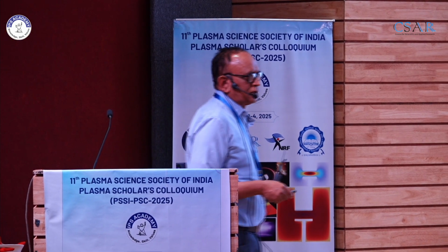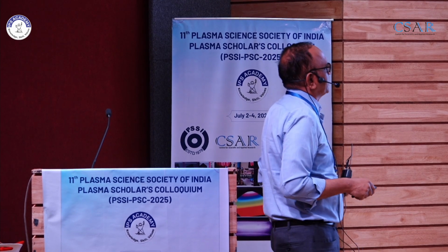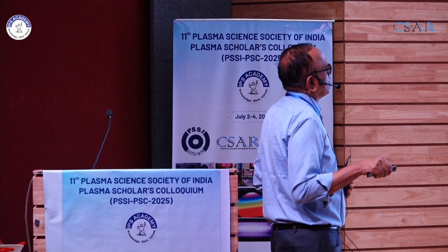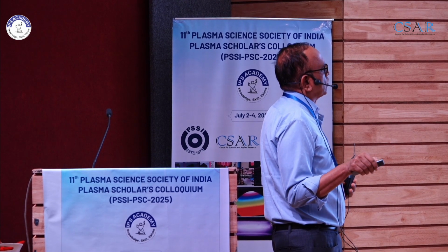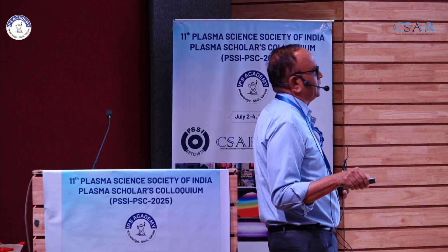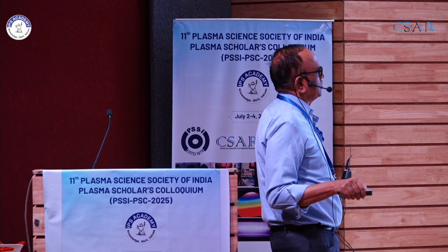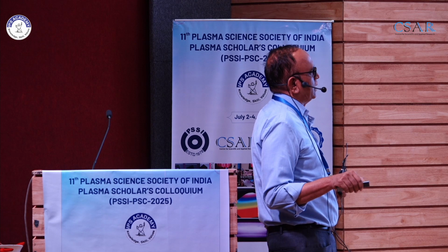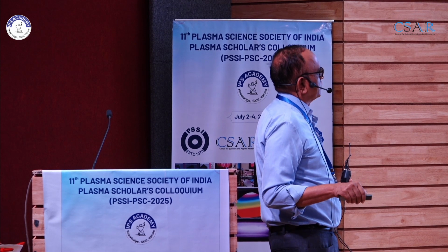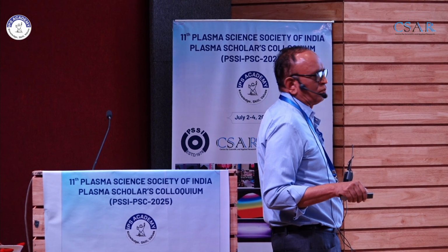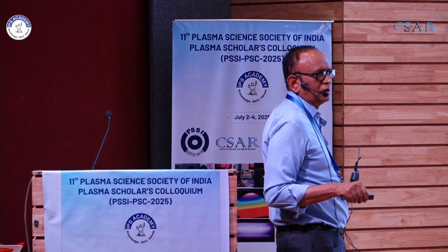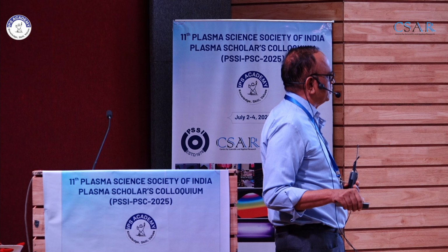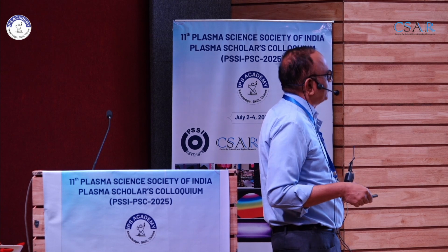of materials. The examples for these low pressure plasmas are large area deposition of good quality coatings, diamond-like carbon coatings, cubic boron nitride coating, nanocomposites, biocompatible coatings, carbiding, nitriding of the surfaces, processing of polyesters and synthetic fibers for changing their wettability and hydrophobic to hydrophilic nature, chemical vapor deposition of exotic coatings, nanoparticle generation, chemical vapor infiltration for making metal matrix composites or ceramic matrix composites, plasma etching, sputtering, etc., and synthesis of new materials.